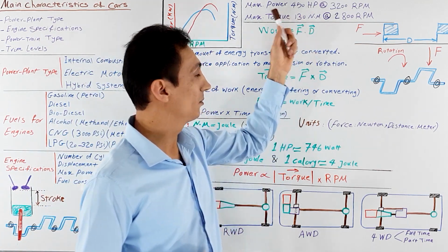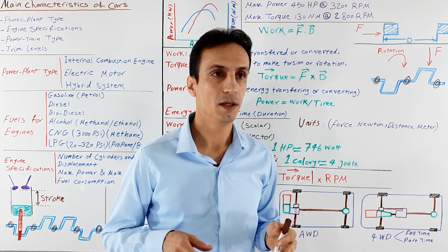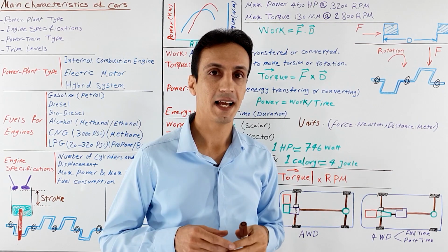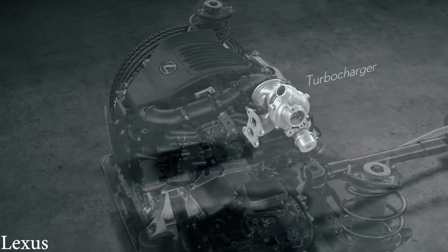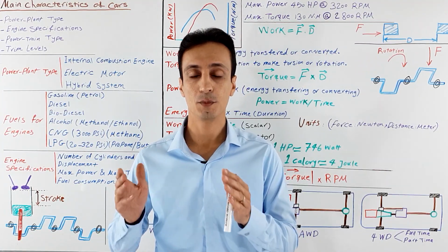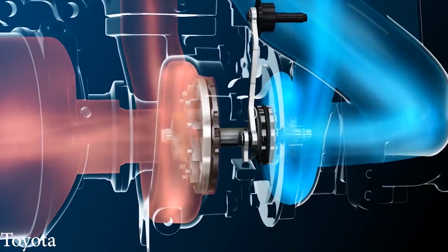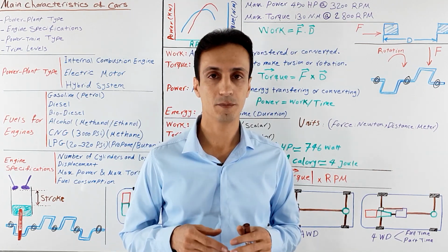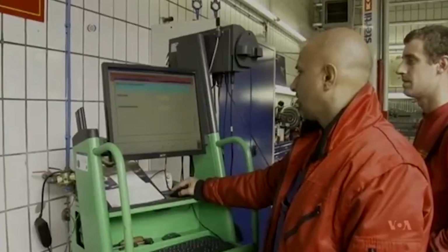To increase these numbers, you can use turbochargers and superchargers, and an engine with a boosted air supply system and fuel consumption as a compromise has a better performance under load. This boost system can be designed by the engine designer or by aftermarket suppliers, and they come in a package called a boost control system. This boost control system is relatively expensive and takes its toll on the engine's life, and installing them at aftermarket shops needs ECU reprogramming that may affect emissions.